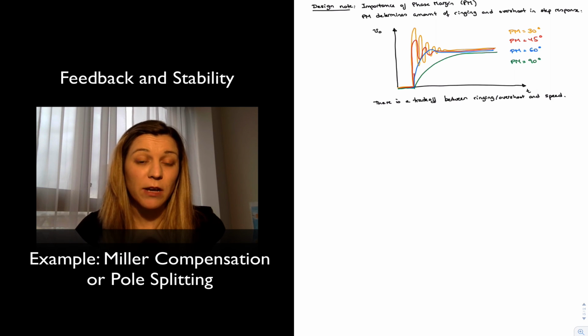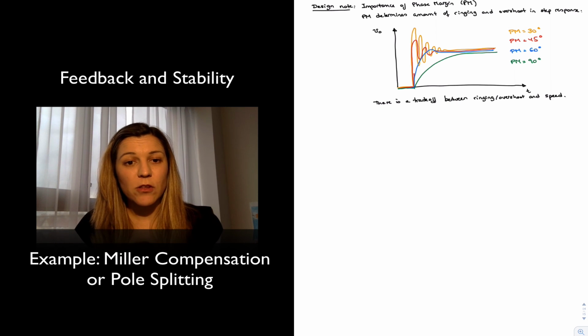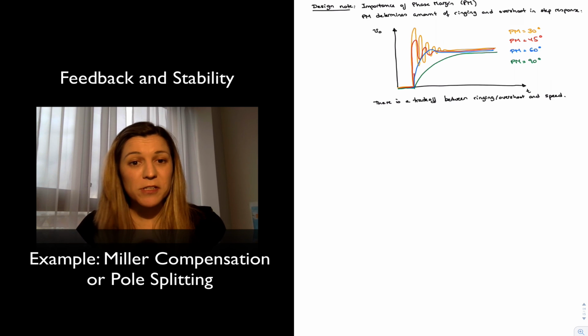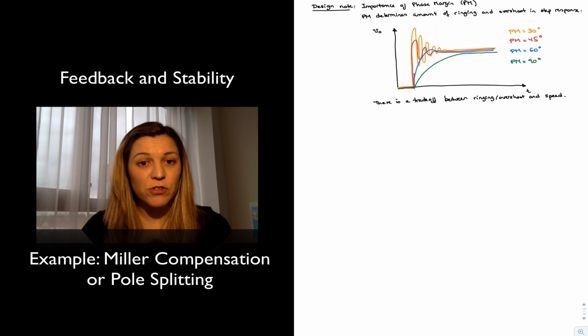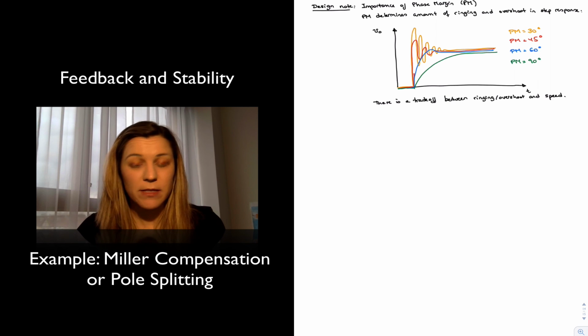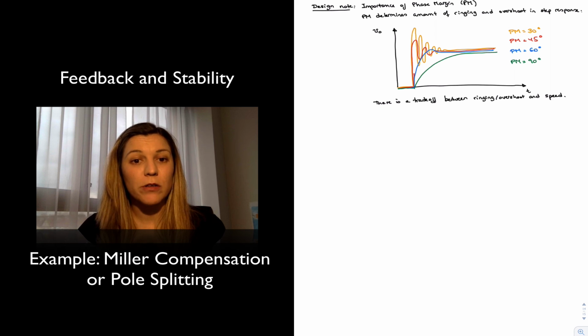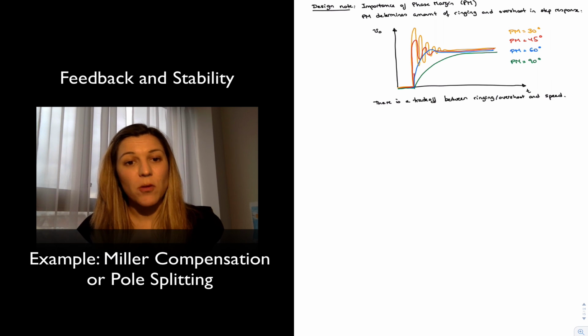Well, it's to guarantee the stability of your system. Why would you want a decompensated op-amp? And that's so that you can hopefully squeeze the last bit of performance out of your system, typically in terms of speed. You will note that the slew rates of internally compensated op-amps are going to be smaller typically than the slew rates of uncompensated op-amps.